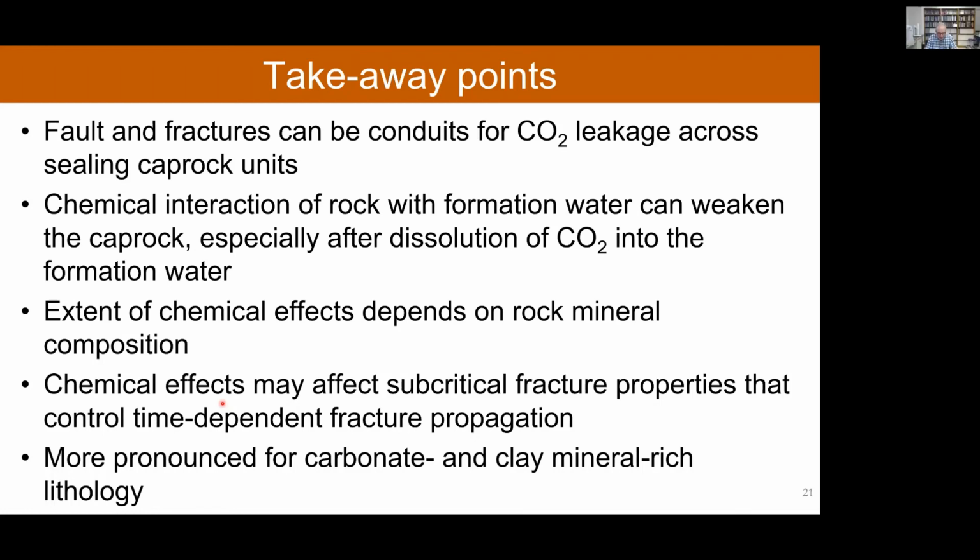So I'm not sure if I get all parts of this question, but I should emphasize, we looked here at fracture growth, right? Or what we call mode 1, opening mode fracture growth. The whole topic of leakage is also reactivating a fault, which is a Coulomb failure analysis, which we have not done here, but that will depend on the rate of pressure increase in the reservoir.